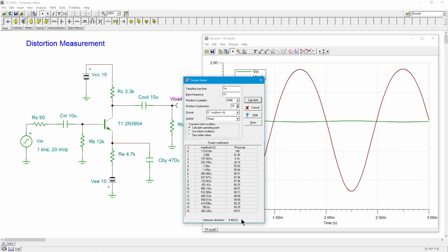If you're talking about a hi-fi amplifier, this isn't. We don't really start talking about hi-fi quality until we get well below 1%. I wouldn't call 0.5% THD hi-fi, right? So 9.4, not so good. Now that might be perfectly fine for an intercom or something like that. You don't really care about super high fidelity, right?